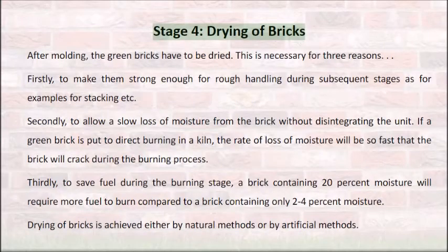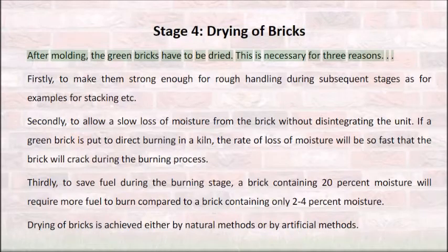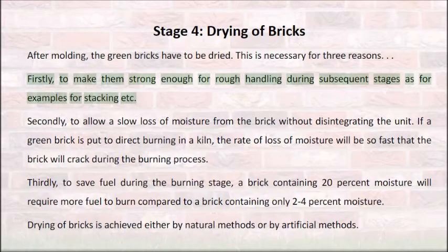Stage 4, Drying of bricks. After molding, the green bricks have to be dried. This is necessary for 3 reasons. Firstly, to make them strong enough for rough handling during subsequent stages, for example for stacking etc.